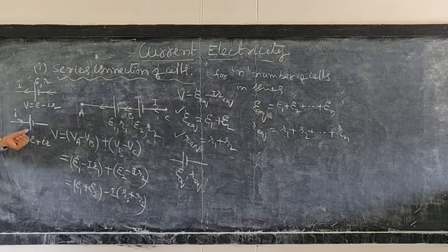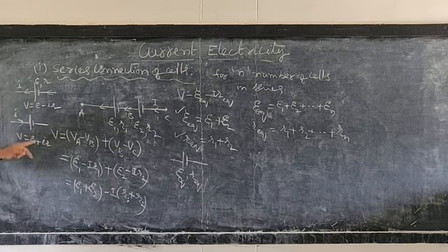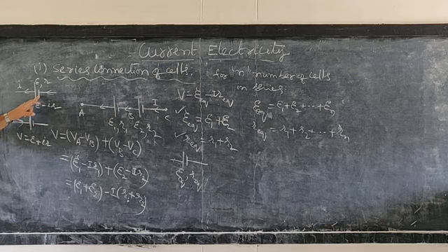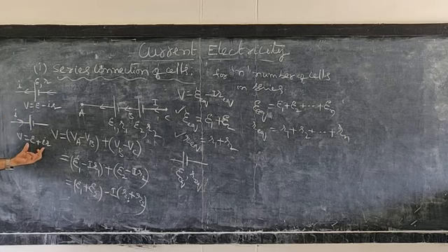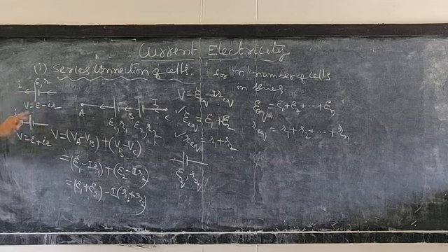Hence, we put minus I here, therefore that will be plus. So when comparing these two, here it is discharging, here it is charging. Here, the potential difference across the terminals of the cell decreases. Here, it will be more than its EMF, it increases. So you should remember there is a difference between these two.